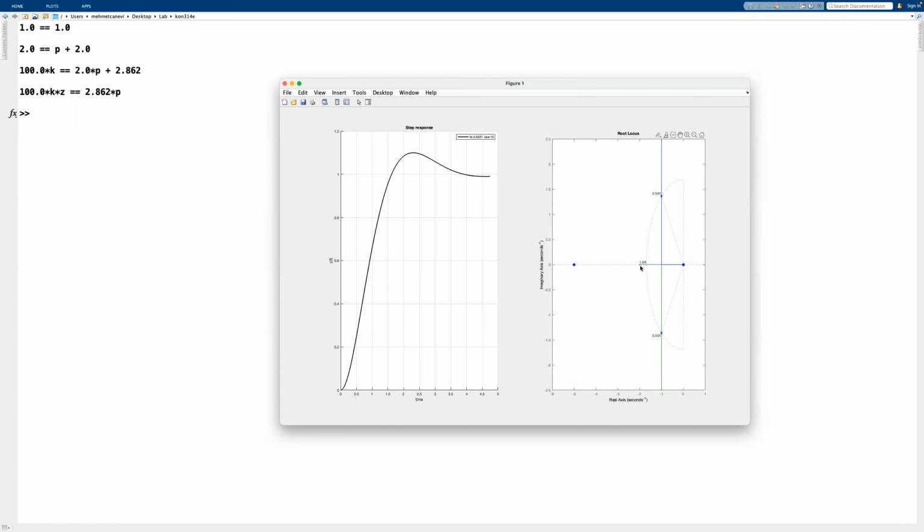I said that if we would have a pole at -2 and another pole at the origin, they would coincide at -1, and our real part would be equal to 1, which is the line for settling time equals 4. So we have to be on this line, and the zeta here provides us the necessary angle, and the intersection of the omega n and zeta gives us this exact design point.